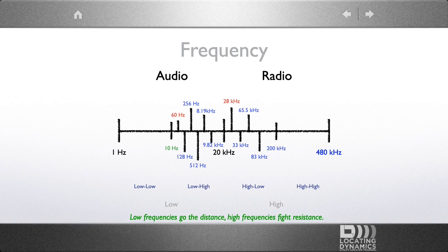The interesting thing about 480 kHz is that it has the potential to jump a broken tracer wire and continue the locate, and push past an insulator if one is present on the line and continue the locate.